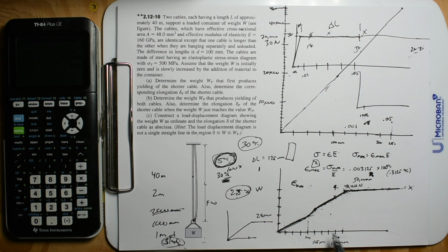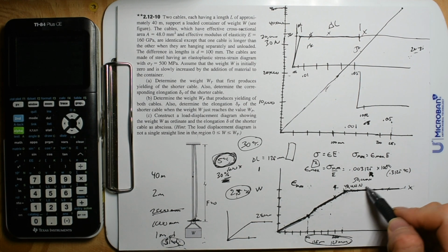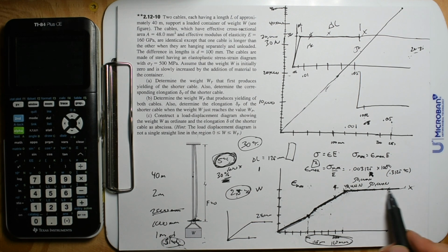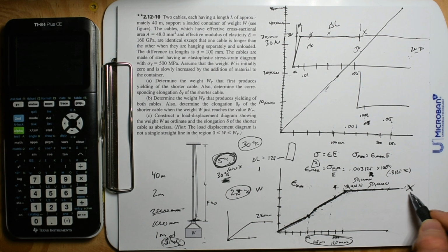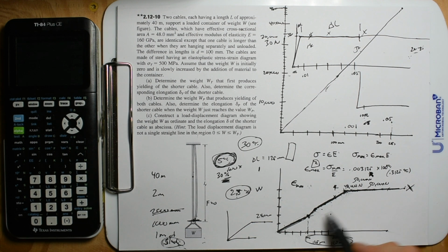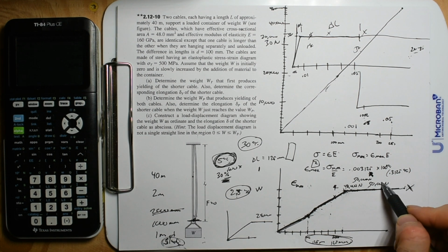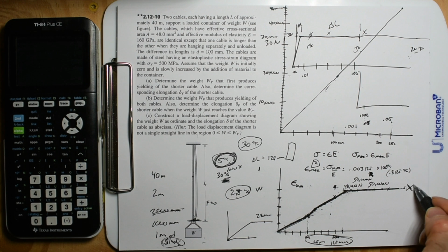So there you go. You can't talk enough about how these small changes in length just past the elastic range are not a huge deal as long as you have something to back it up. But in this scenario, if you put more than 50,000 newtons in this cable, you're just going to stretch and break, and you're probably not even going to see it stretch. You're just going to know based on the properties of the cable. But the second you pass the strength of both cables combined, see you later, and that weight's hitting the ground.